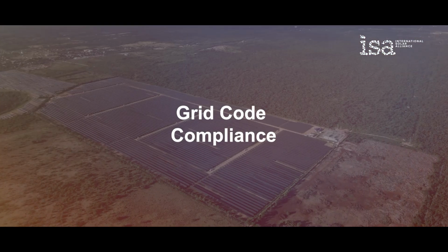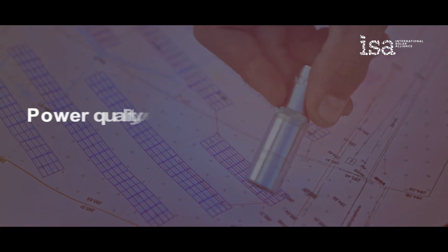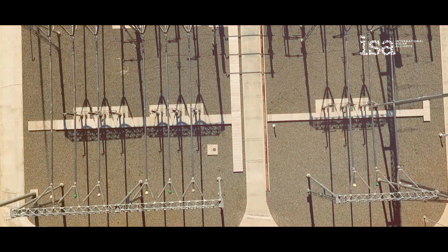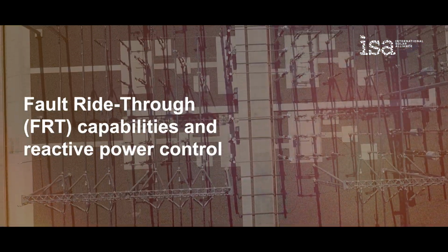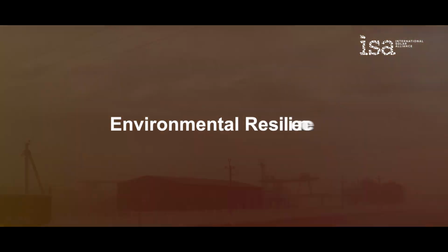Grid code compliance. Large solar plants must adhere to strict grid codes regarding power quality, voltage, and frequency variations. The substation design incorporates features like fault ride-through (FRT) capabilities and reactive power control to meet these regulatory requirements and avoid operational penalties.